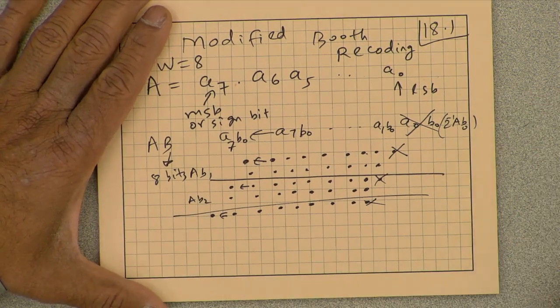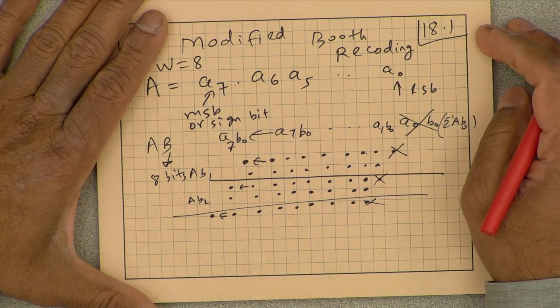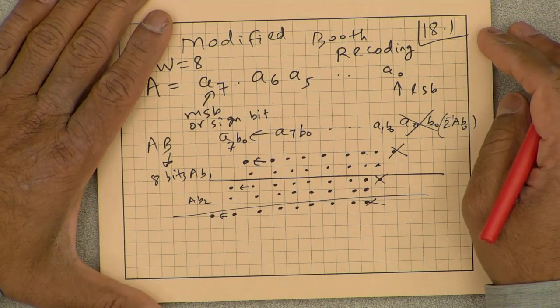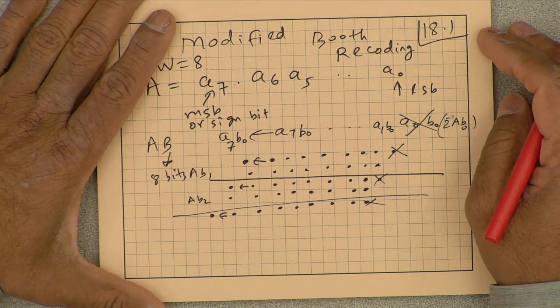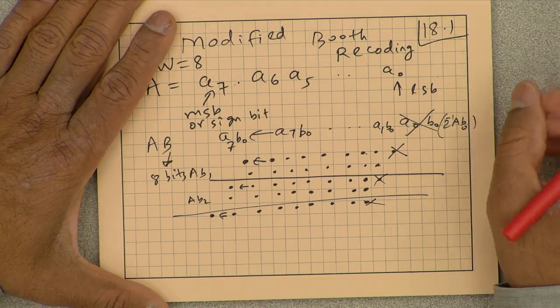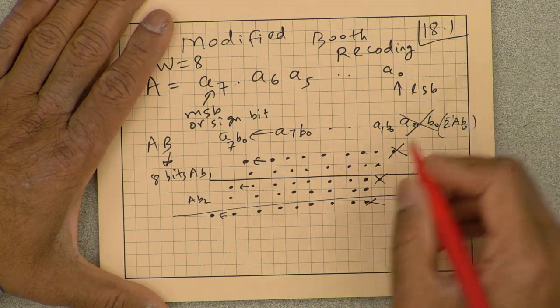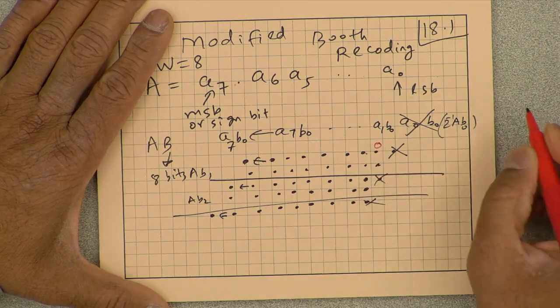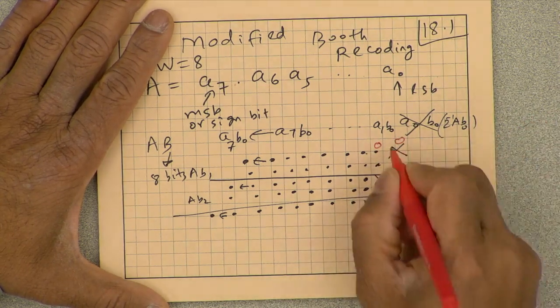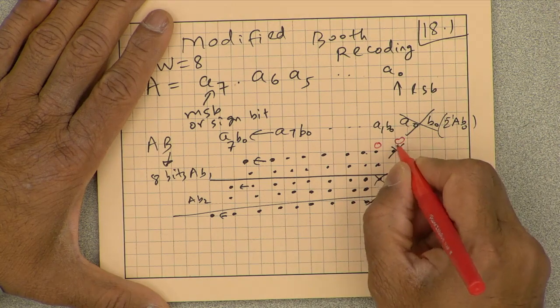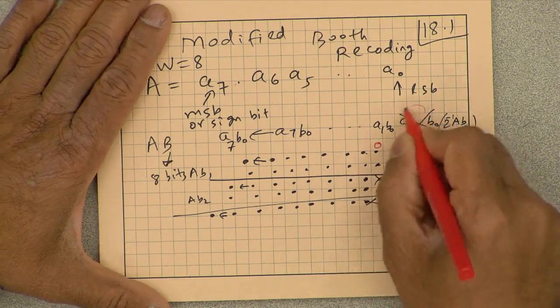So now let's just say that each of this is pipelined by the whole thing. Think about this carry ripple multiplication process as pipelined by a 1-bit adder. So everything is pipelined at the level of a 1-bit adder. If I start this operation at clock cycle 0, this is A0 B0.